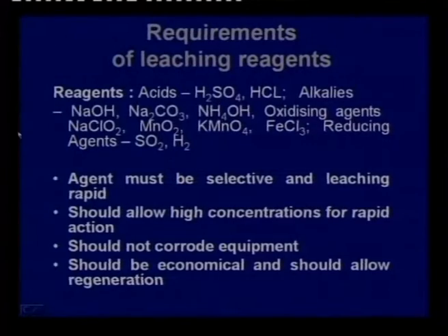So, the whole idea is the agent must be selective, leaching must be rapid, should allow high concentrations for rapid action, the leaching reagent should not corrode equipment, it should be economical and should allow regeneration. Now, there are a whole range of things used in leaching.